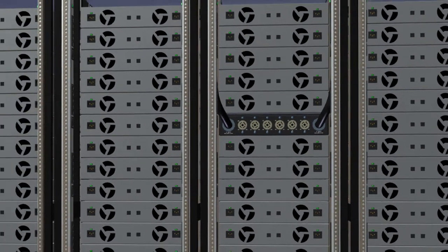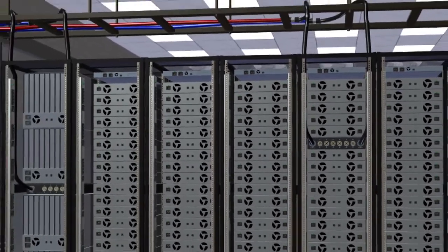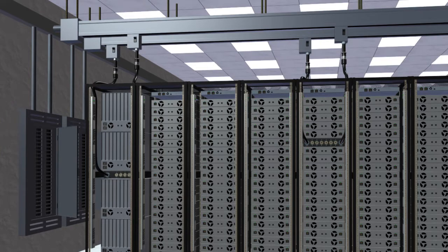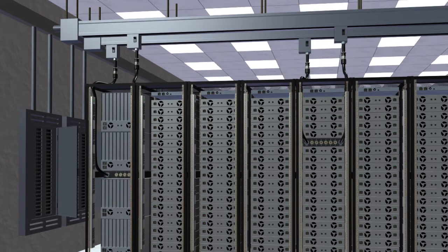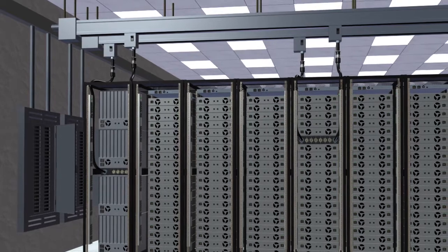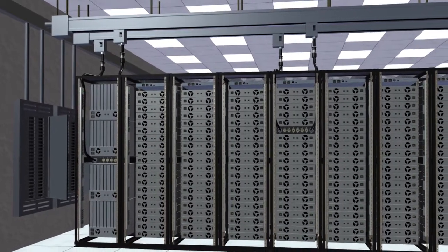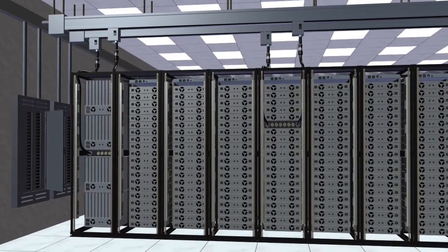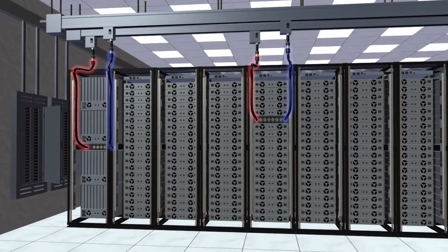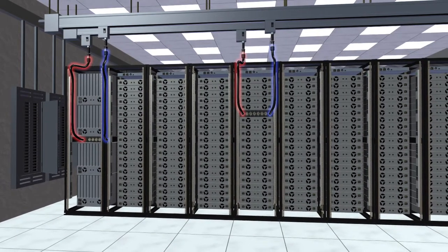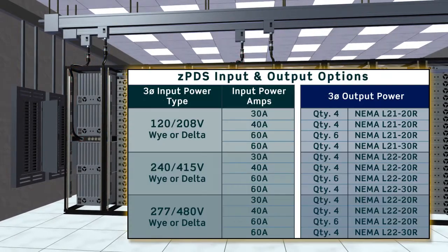Third, the upstream parts of the infrastructure, option number 1, panel boards and whips, or option number 2, busways and tap boxes, are insulated from almost all changes and also become much easier to design, build, and maintain. This is because they are now very simple. Just place uniform AB pairs of 3-phase receptacles on the end of the whips or in the busway cans, based on the power density target you choose for each set of racks in the data center.